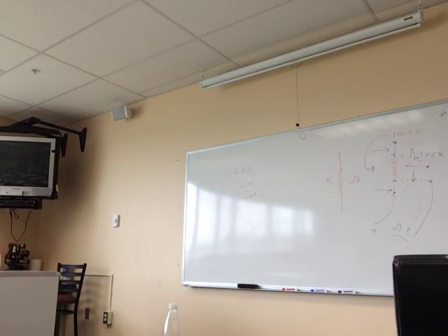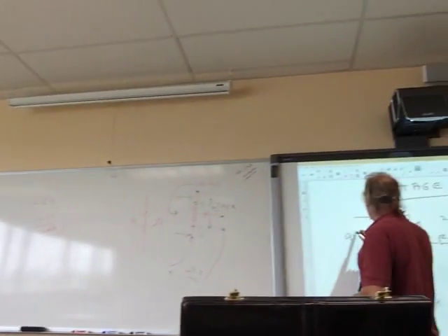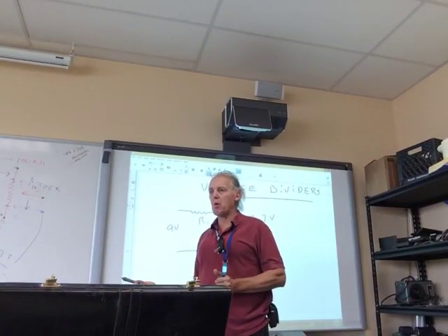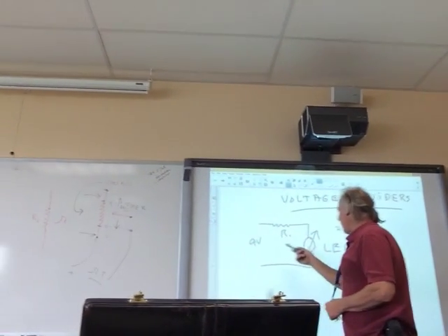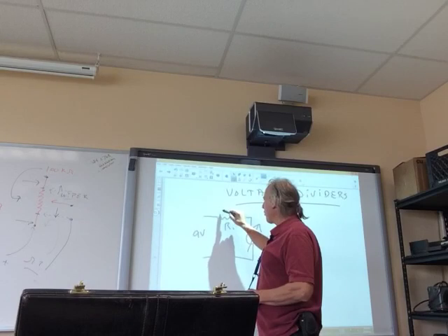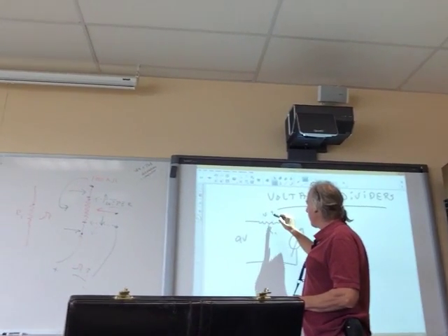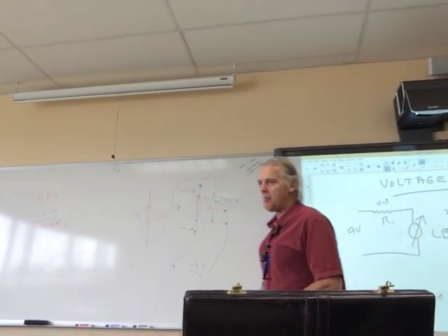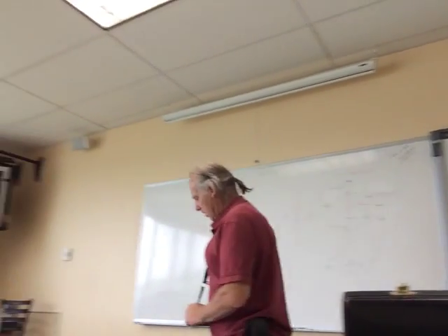An LED is 2.7 volts. If I have a 9-volt battery, I have to do something to make sure it doesn't burn up. In other words, whatever 9 minus 2.7 is, R1 has to drop that voltage or the LED goes away, right? Okay. You can use a bigger resistor.